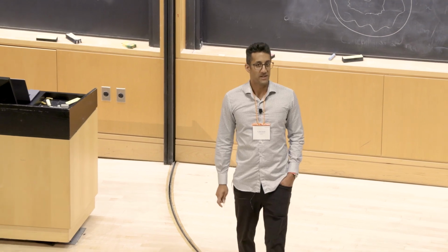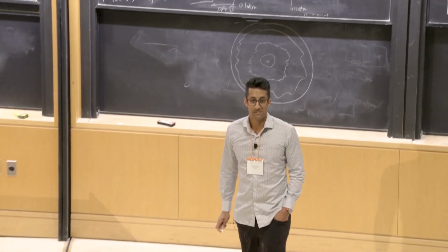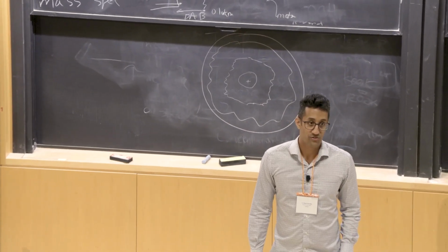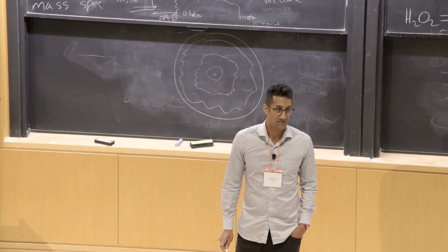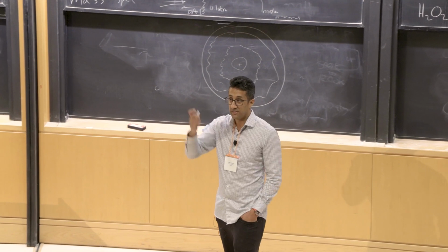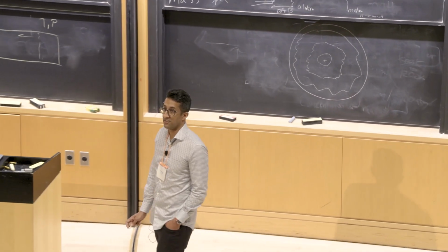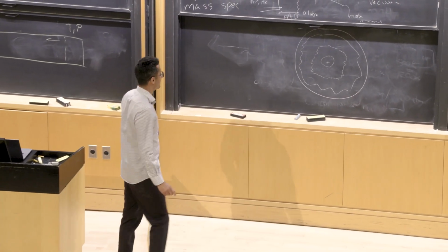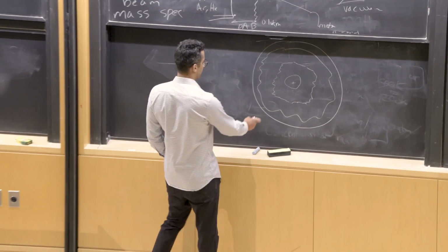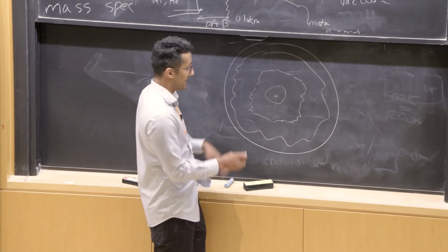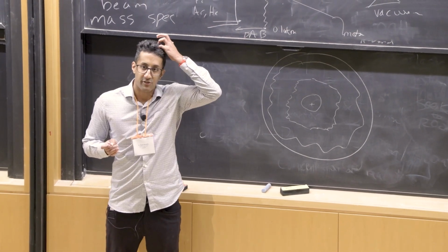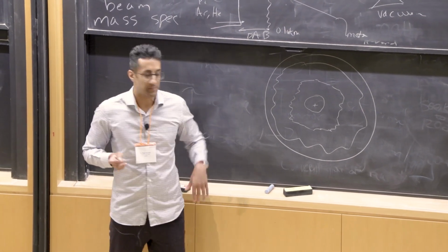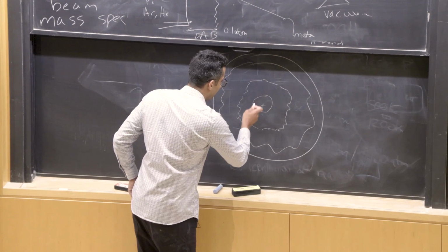Turbulence. Well, there's not necessarily mixing here. Okay, stretch-induced instability. Hydrodynamic. This is mainly hydrodynamic instability. And once this starts happening, the flame is no longer smooth. You don't know where the flame surface is. So, in order to measure the flame speed, they need a very nice round flame.